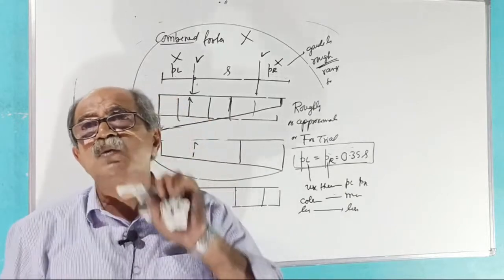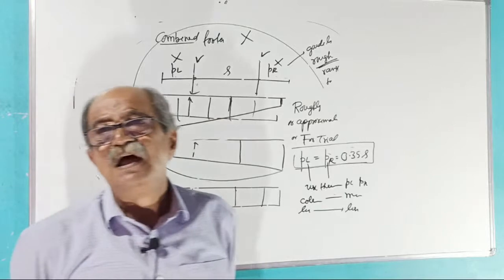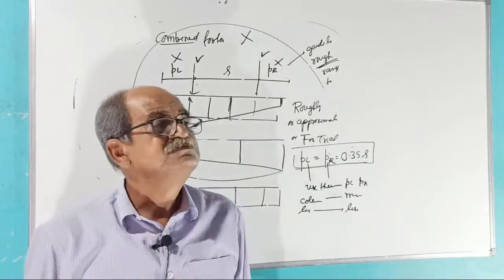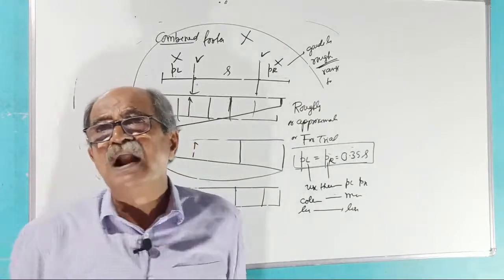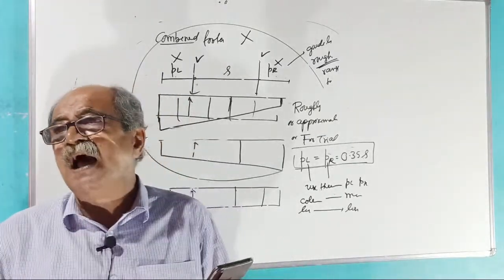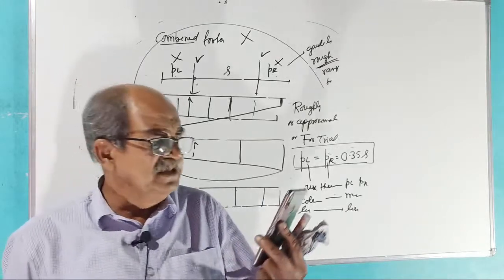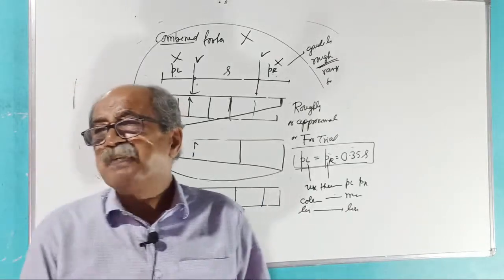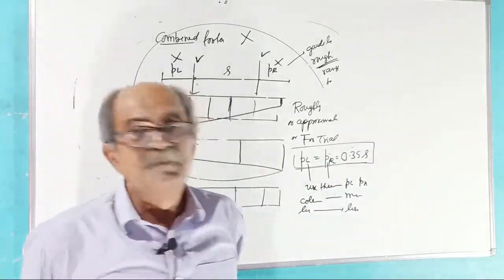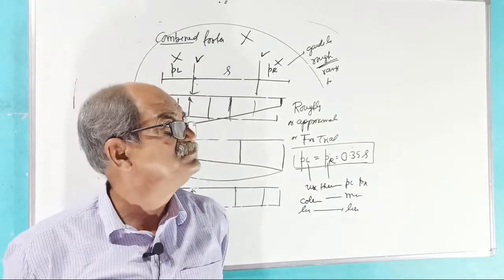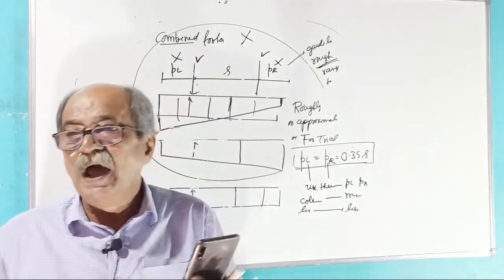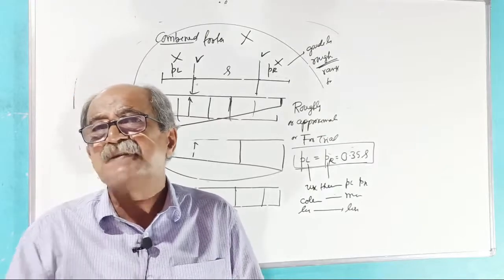Uniform pressure has advantage. Tell why. Reason first: if pressure is uniform, settlement becomes even or uneven? If pressure is uniform, it becomes even. If the settlement is even or uniform, good or bad from the stability point of view? It is very good. Uneven settlement creates problems.